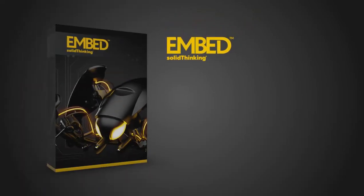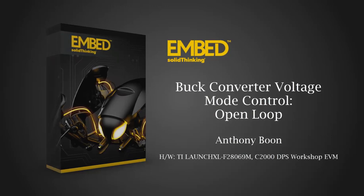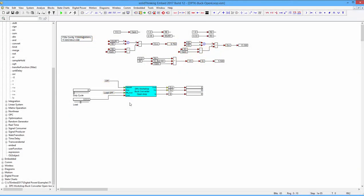Okay, so in this video we've got not the same control diagram at all. This is first an open loop attempt on the buck converter, so that we should be able to control the duty cycle here and vary the output voltage in an open loop. With this slider here, we can vary the load on the buck converter.